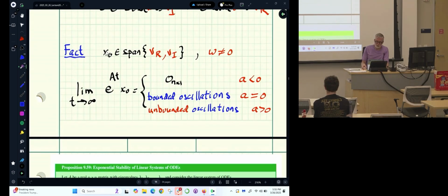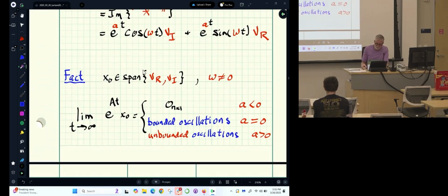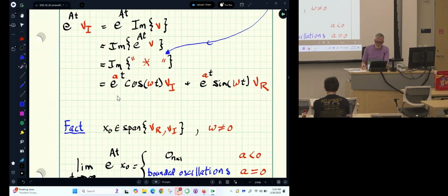That's what allows you to understand how to choose real initial conditions. Because you're saying, I can't initialize my RLC circuit with a complex eigenvector. What do I care about complex eigenvalues and complex eigenvectors? Well, you can initialize it with the real and imaginary part of that eigenvector. And you see exactly the same behavior as we saw in the real case. So you've got oscillations. You still have the real part determining expansion or contraction. And it's times components of the eigenvector.